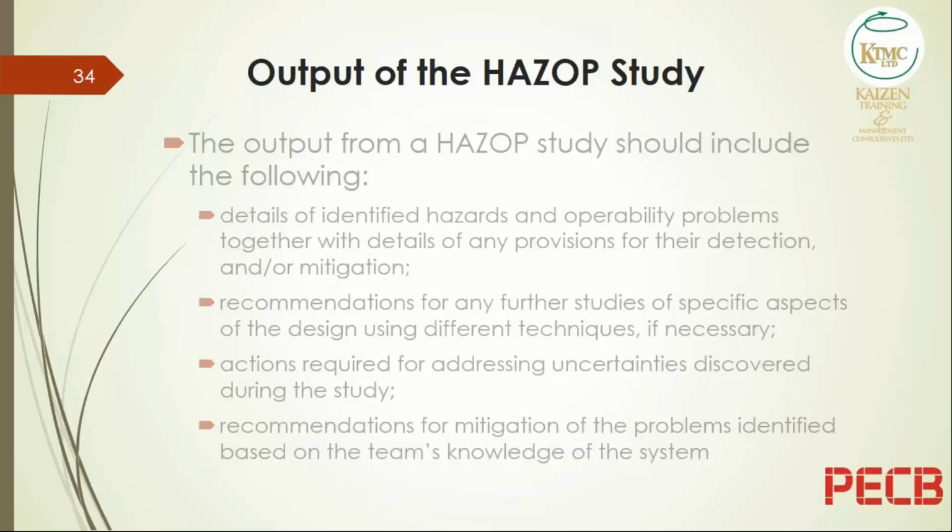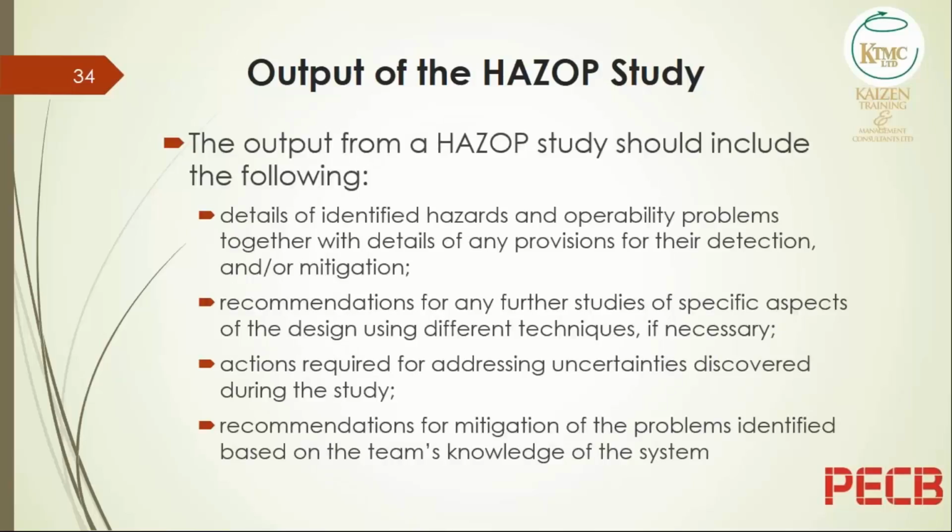The output from the study details the identified hazards and operability problems, along with details of any provisions for detection and/or mitigation. And typically, we have assignment of responsibility as we go along. Recommendations for further studies could be a key output as well. Actions required for addressing the uncertainties discovered during the study. Recommendations for mitigation.